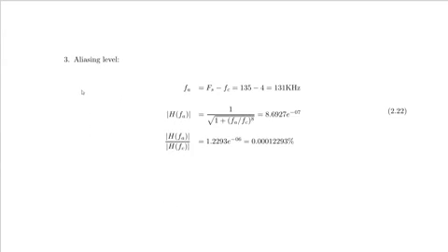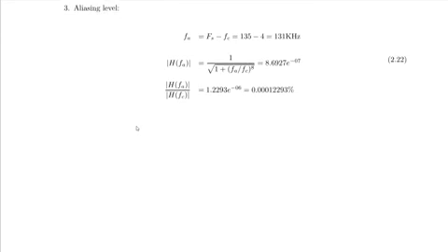In order to have the recording length shorter, we have to hurry somehow. Aliasing level. FA will be Fs minus Fc, leading to 131 kHz. What about the aliasing level in this case? It will be really negligible, so don't worry about aliasing level. It won't have any harm.